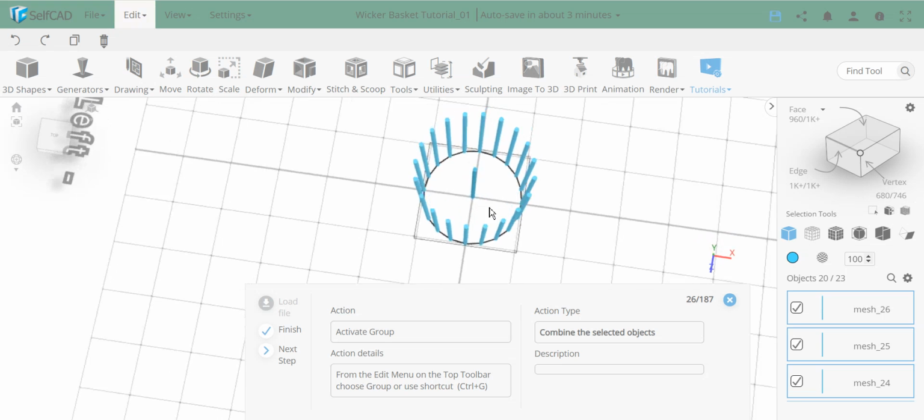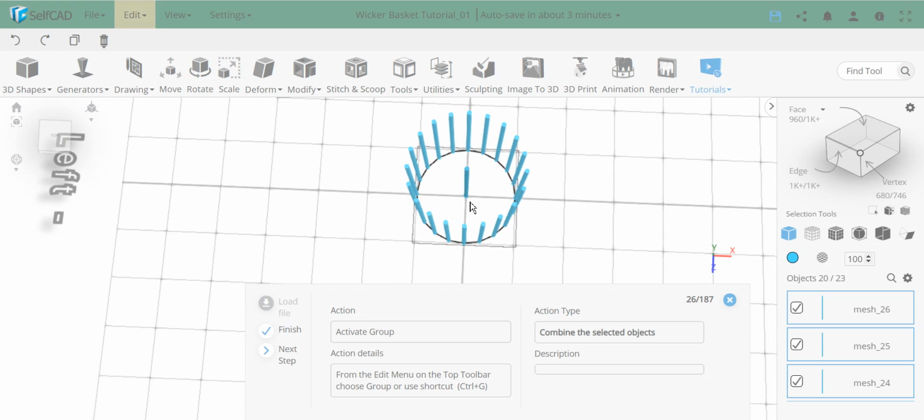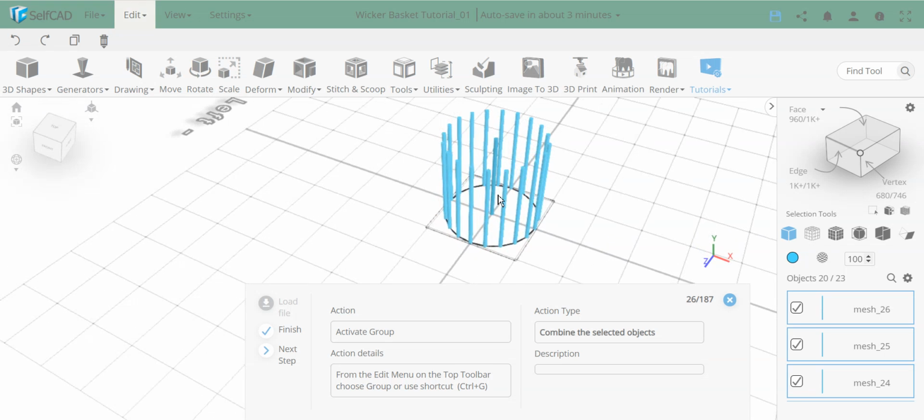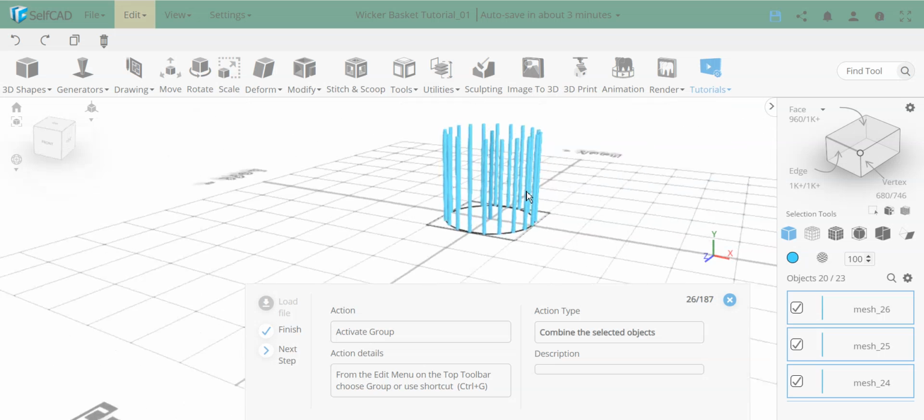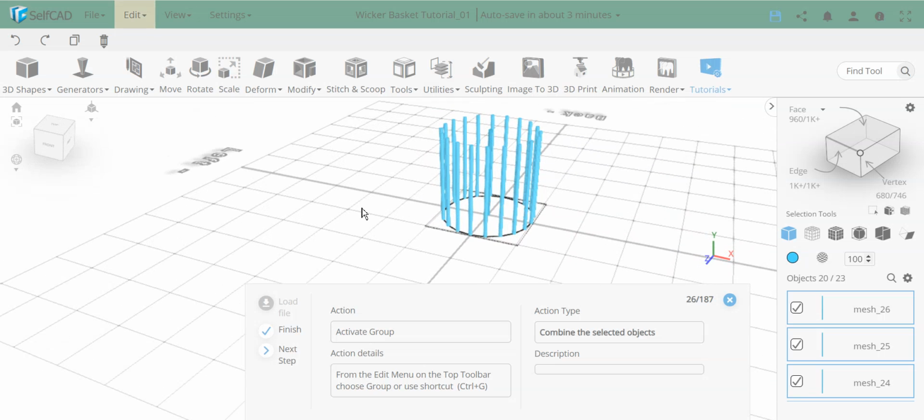But actually in that case, you would have needed to move it, because the pivot will go around the center of the scene. So in order to use the pivot, you would have had to take this cylinder, move it away by half, basically the radius, set it over here, and then you can use the Pivot tool, which will automatically make the copies, the amount of copies you set. In this case, the Follow Path did the same thing. So it's just a different way of doing it. Just good to know the different options.